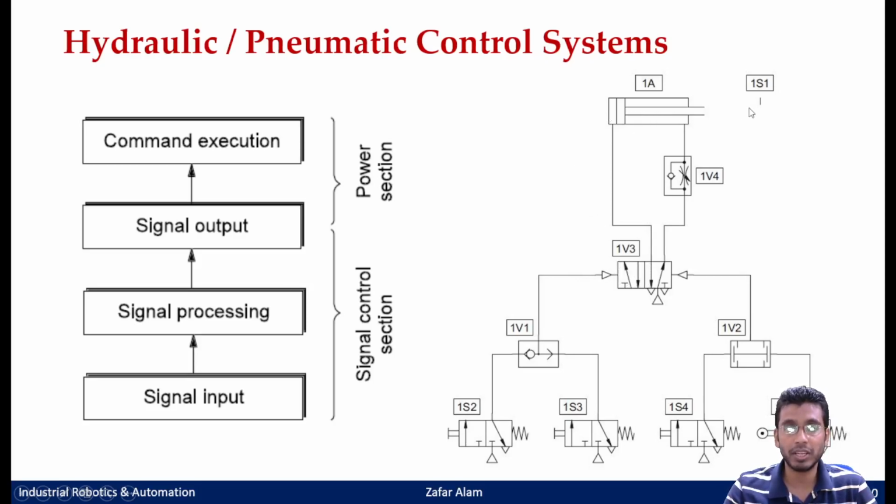Okay, so with this pilot line, this position would get engaged and your double acting cylinder would extend. Okay, now once the double acting cylinder is extended, the other circuit you are making is using an AND valve. Once it has reached its end position and you press another switch here, then again you get a signal back here, and that would shift the valve to its default position and your cylinder will retract. Don't worry too much about this circuit, we will be designing this circuit again.